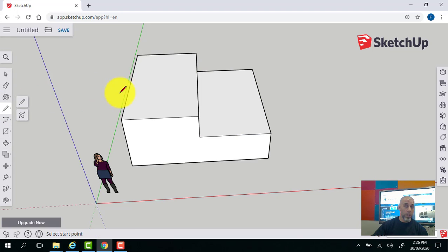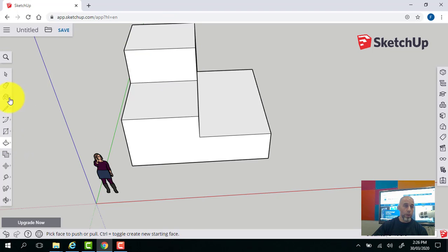Okay, so the same thing, you can almost do any sort of shape that you want, push and pull, and you'll be able to just play around with normal shapes. Now, if I was to go back to the rectangle area and grab the actual circle, I can then make a circle on the actual face, and then you'll be able to push it in or push it out.